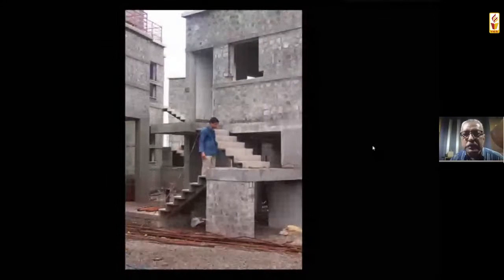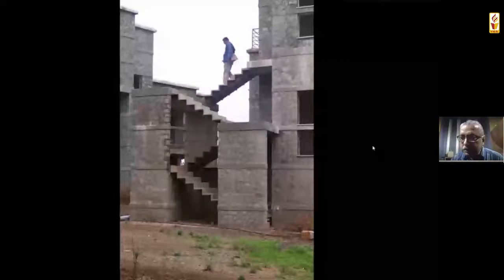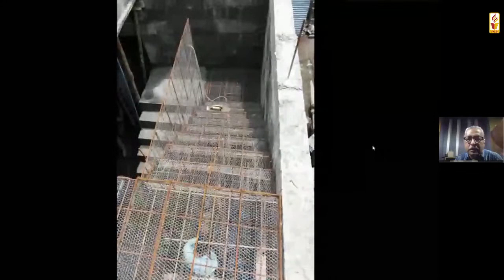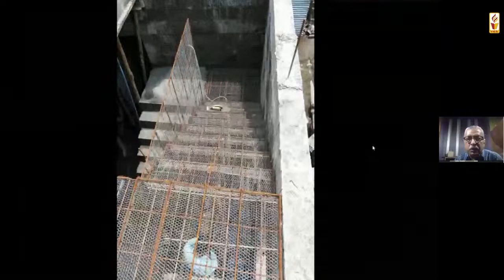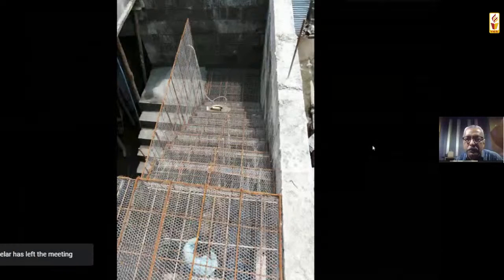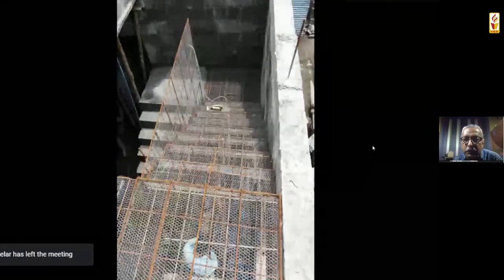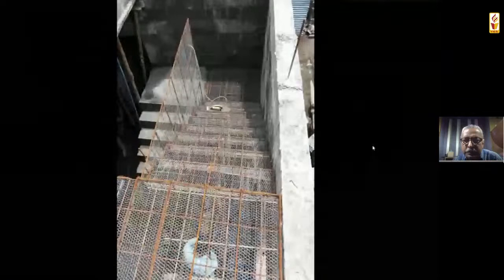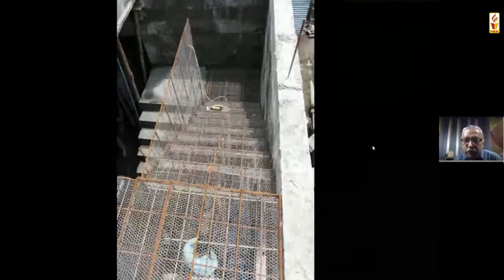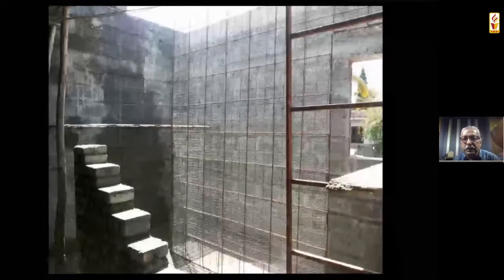And then you can see very beautiful housing. This is in Ahmednagar, which happens. So with this folding thing, we started doing a lot of staircases, and a slab under the toilets where you need a sunk. Otherwise slabs are 200 mm thick, but when it comes to a toilet, then you can have a sunk of 200 mm. And because the thickness of good ferrocement is about 25 mm, you get quite enough space for pipe to go from here to there. And you can see very beautiful vertical walls which are done with this method.